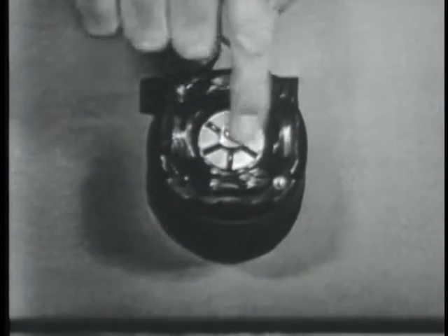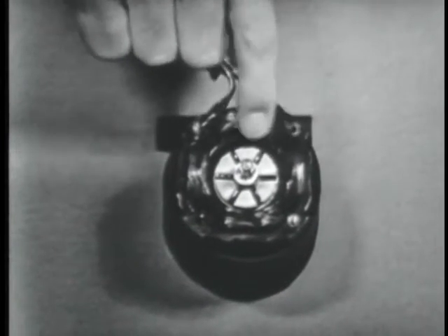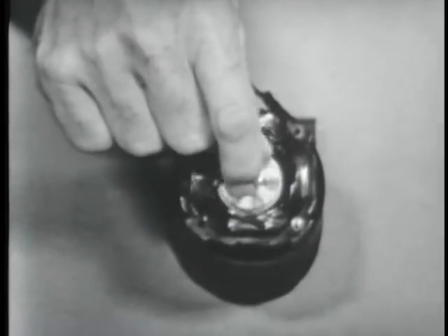In the induction motor, the moving or rotating magnetic field is supplied by the stator field windings. And the rotor follows this field movement because it becomes an electromagnet. In other words, when current is applied properly to these windings, a magnetic field is generated that rotates about the housing. Now, the field windings do not move themselves, and this rotor is not a permanent magnet.